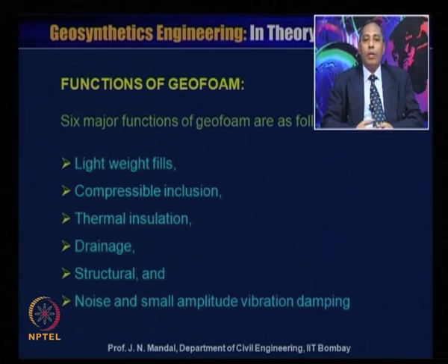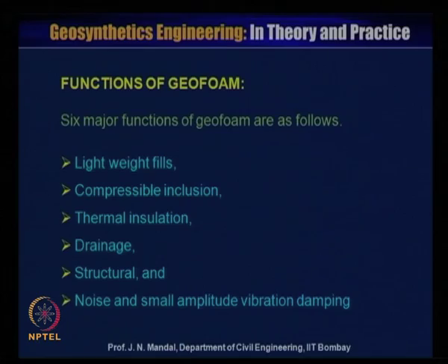I have also shown you earlier how this material has been used for the different functions: in the construction of embankment, where it can be used as a lightweight fill material, or at the back of the retaining wall, where the geofoam material acts as a compressible inclusion, or where there is storage or temperature control, how you can use it as thermal insulation.